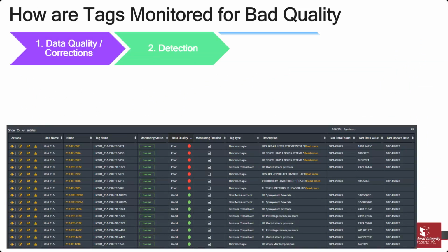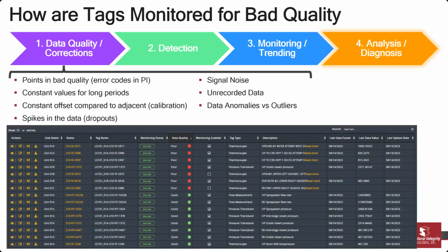So one of the things that we quickly got into is we needed to implement a bunch of data quality checks into the code to detect, are there outliers, are there anomalies in the data, are there constant values, dropouts, thermocouples detaching. And so this is just, for your knowledge, thermocouples in general are fairly easy to attach, but if you're going to use them for any amount of monitoring and damage calculations, you need to validate that data going in and coming out is good.